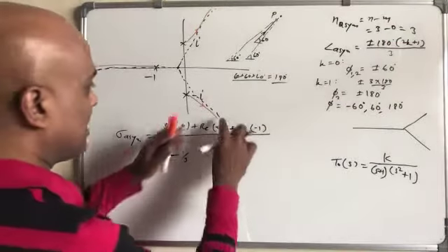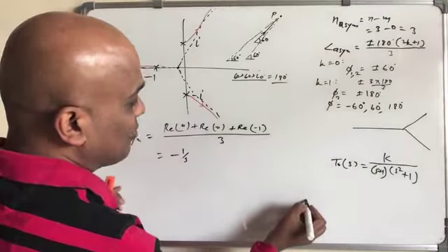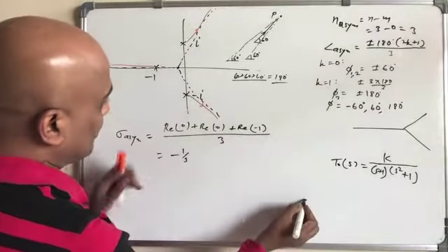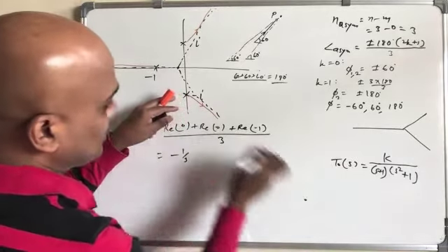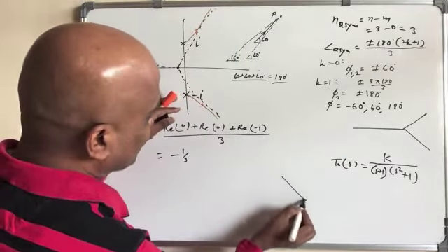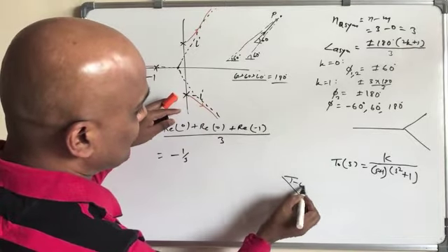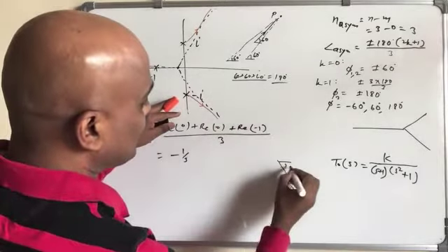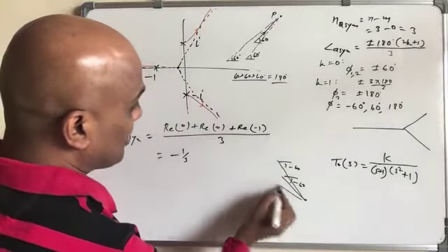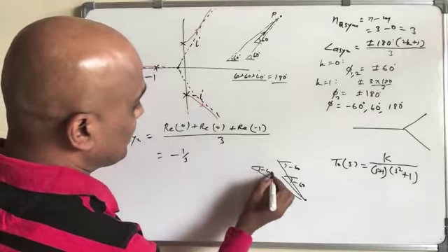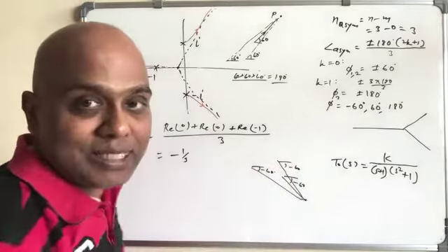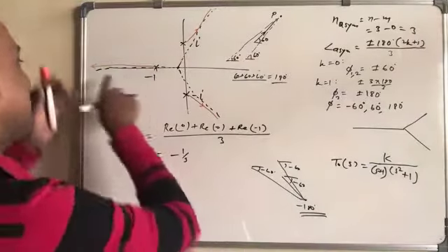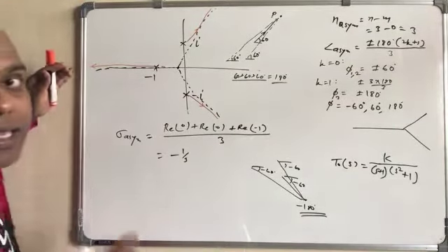Same thing you can do here. If you are very, very far away, a point here, what angle it makes from this point, like this one, is minus 60 degrees. From here also, this point will be minus 60 degrees, and from this point also minus 60 degrees. You add all three, it becomes minus 180 degrees, which is required. Similarly, you can do here. Similarly here.